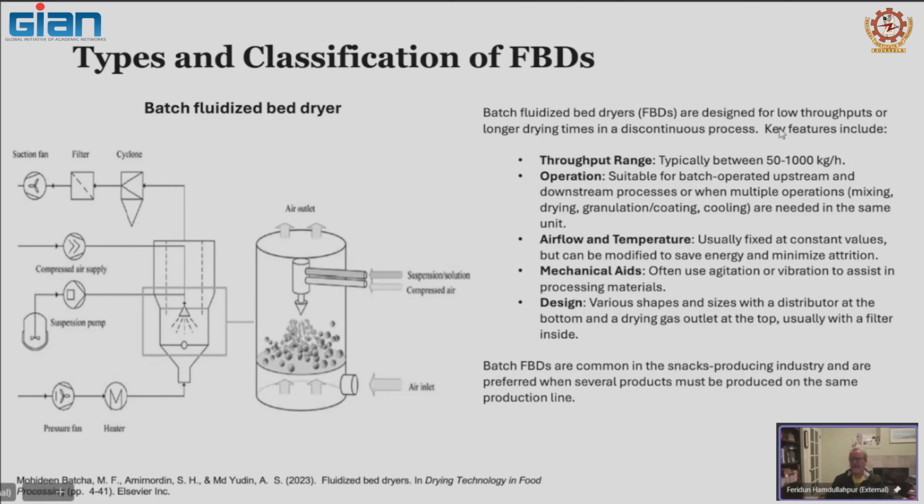And design is relatively simple. You have your particles, grain, whatever you want to dry, going through here. You use, in this case, a little high pressure air because it won't go through on its own, so you have to provide pneumatic transport like conditions to push it through here. It comes downwards in the opposite direction of the hot air, and it's dried within a prescribed time period, and then poof, you take it out and put in another batch.